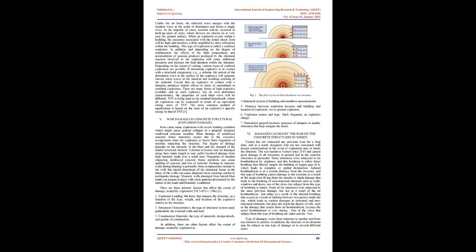There are many forms of high explosive available, and as each explosive has its own detonation characteristics, the properties of each blast wave will be different. TNT is used as the standard benchmark, where all explosions can be expressed in terms of an equivalent charge mass of TNT. The most common method of equalization is based on the ratio of an explosive's specific energy to that of TNT. V. War damage on concrete structural explosion damage.